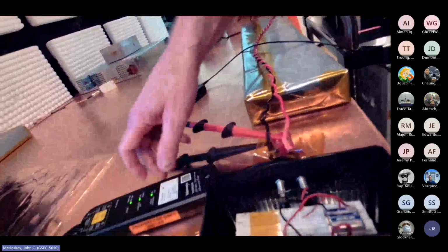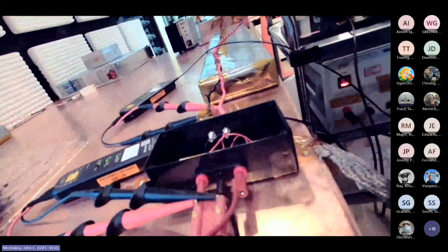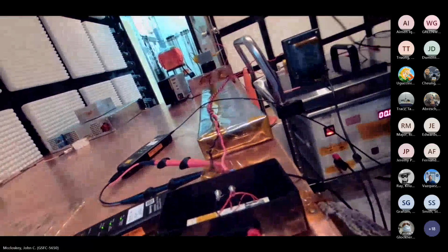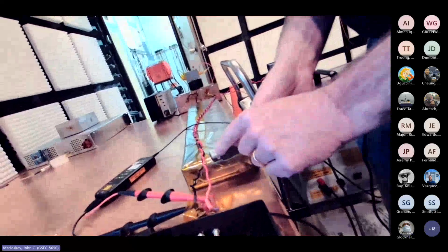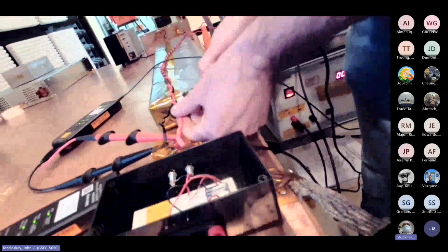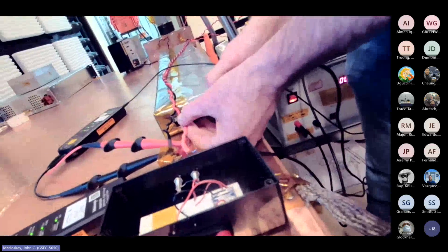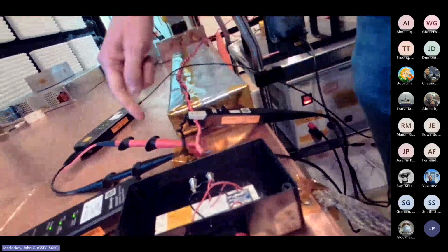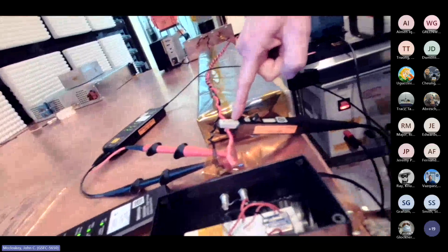And we have a second one here that's monitoring the voltage output. So let me get the current probe hooked up, and then we'll talk about that. So we're going to move the current probe over to the input as well. Here again, in this case, I do want to pay attention to the direction of the current. So there's our arrow that's going to be going into the EUT input terminals. It's a pretty beefy wire. It's power, right? So the current probe is just big enough for it. So now we're looking at the voltage going into our 28 volt feed and the current.